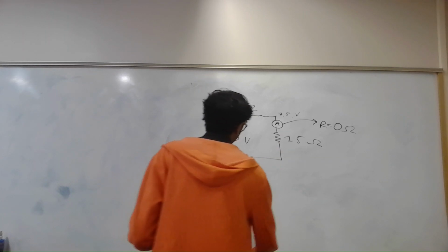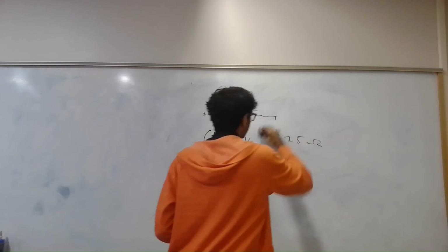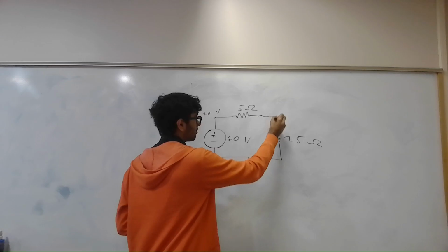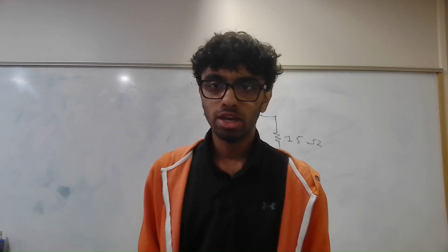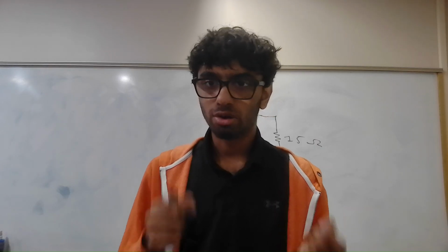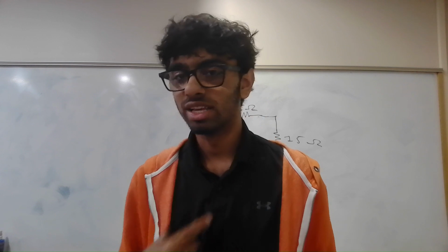Now, what about if I wanted to measure the voltage? Voltage is a little more subtle, okay? Because on top of the fact that there's still some restrictions on what we can change and what we can't change, voltage is always measured with respect to a reference point. And ground in the circuit is not ground of my measuring device unless I connect them, okay?